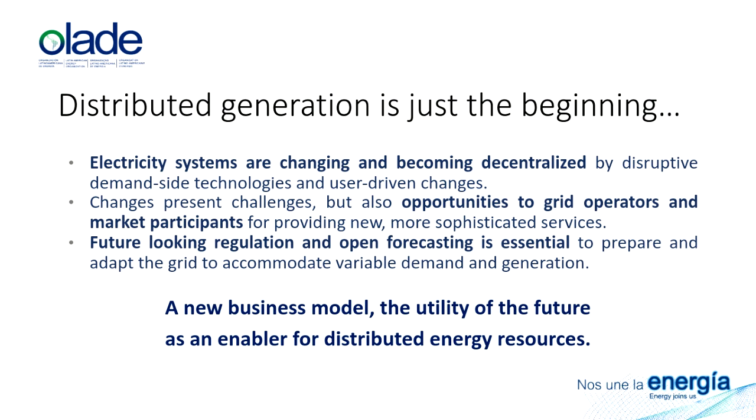Because as you can imagine, it's an island, so it's an isolated system that has a very high penetration of distributed generation, and they are starting to see what the impact is to voltage, as we mentioned, capacity factors and power factors, and harmonics, and what the real impact is to the grid when you really have a lot of these systems. Because before that we have a lot of academic research, but there's not a lot of on the ground examples that you can analyze with a lot of this generation.